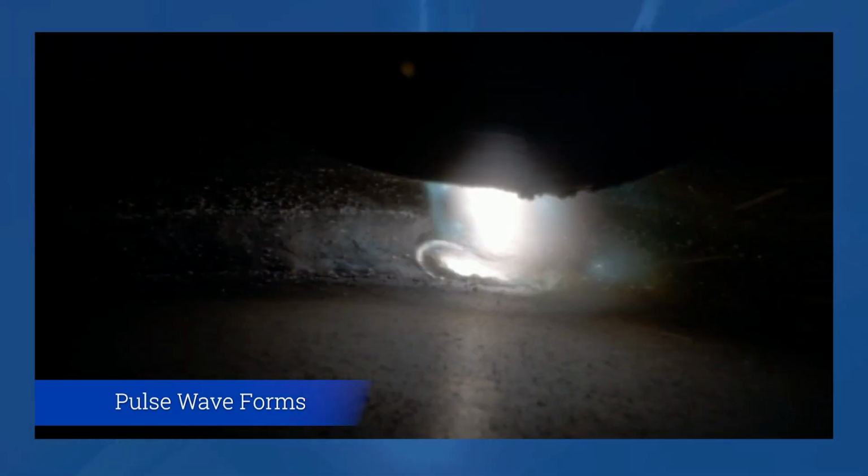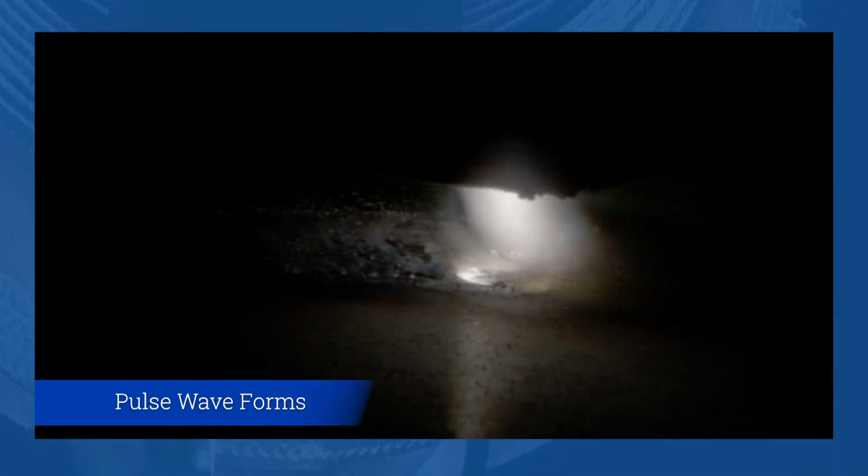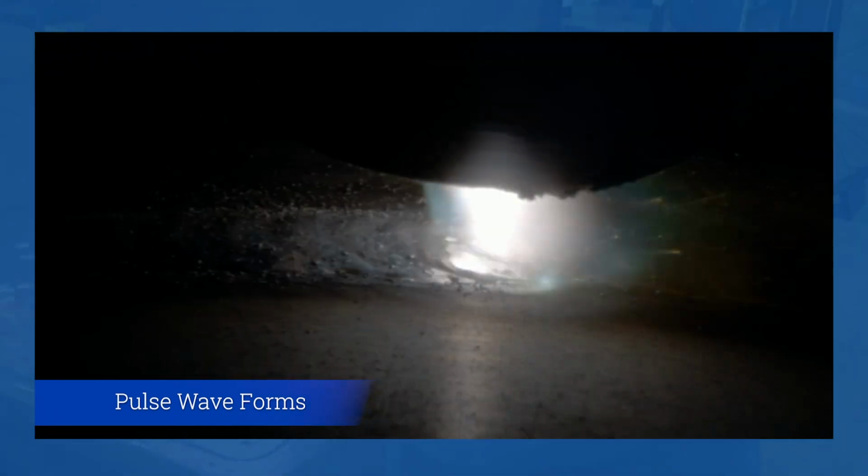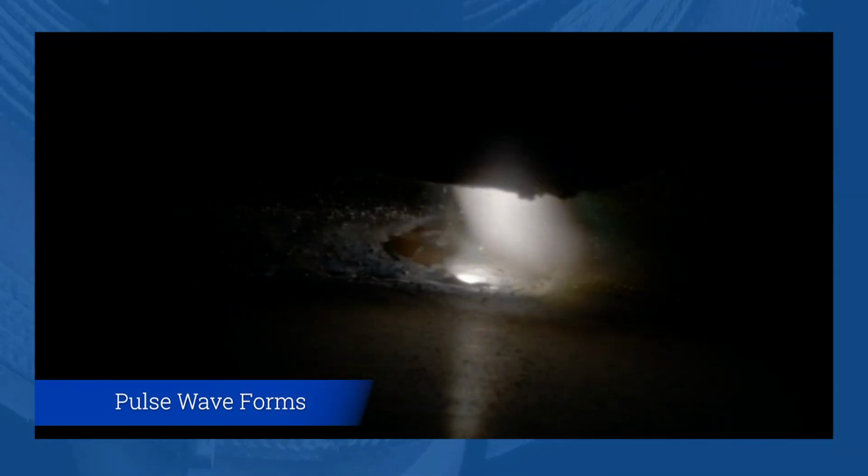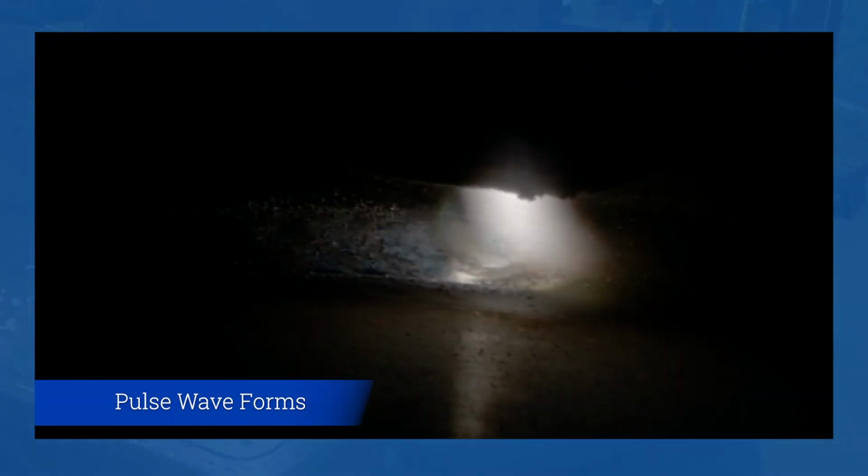So now we've kept the travel speed the same, but we've slowed down the pulse frequency. We're still running a 50% background, but we're not getting enough pulses per inch. This is more like a series of spot welds than a real weld.